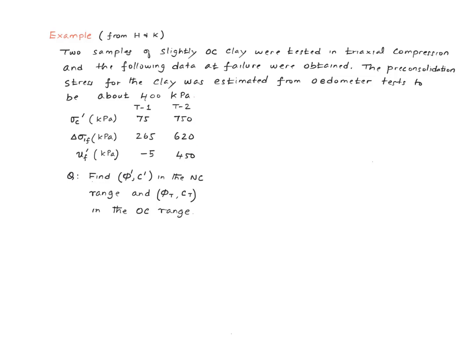The pre-consolidation stress for the clay was estimated from an oedometer test, which is the one-dimensional consolidation test, to be about 400 kilopascal. The question is to find the effective shear strength parameters in the normally consolidated and over-consolidated ranges.